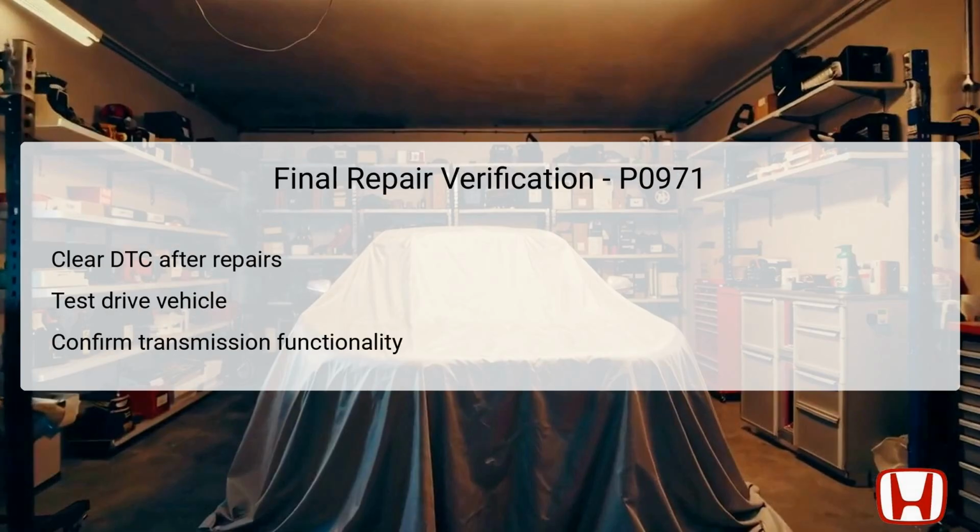After performing the necessary repairs or replacements associated with the P0971 DTC, it is essential to verify that the issue has been resolved. Begin by clearing the DTC using the HDS to reset the vehicle's diagnostic system. Following this, a test drive is crucial to assess the overall functionality of the transmission under normal driving conditions.